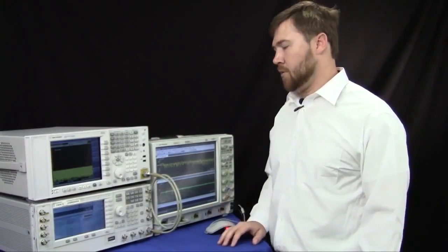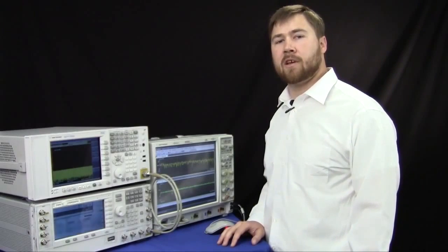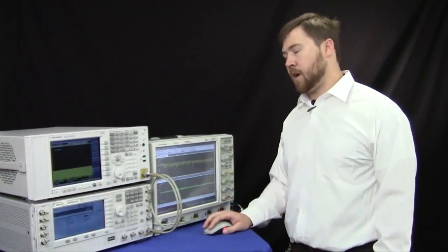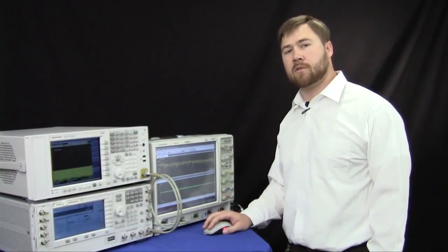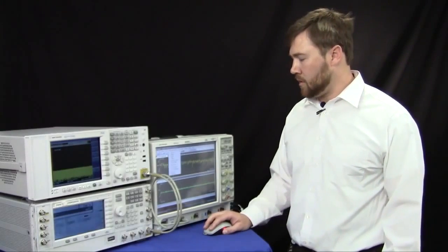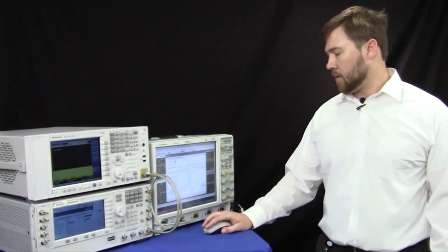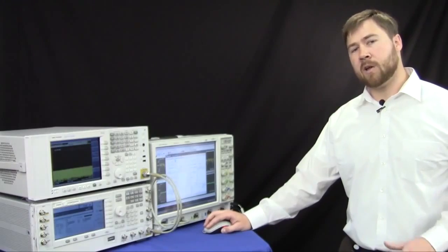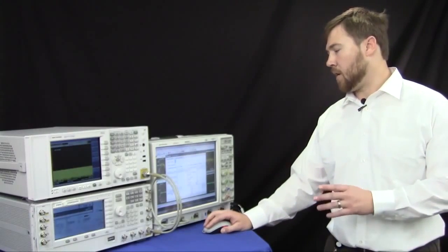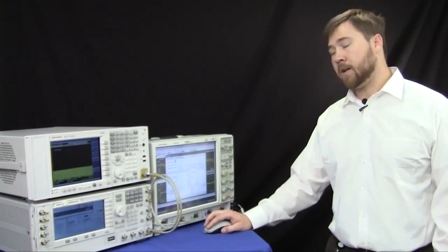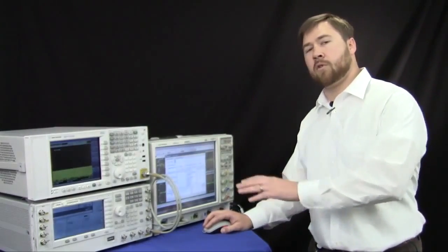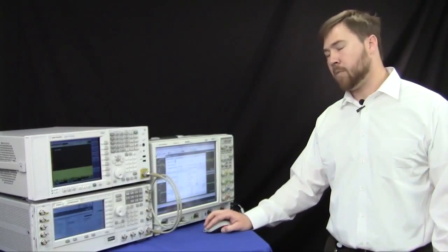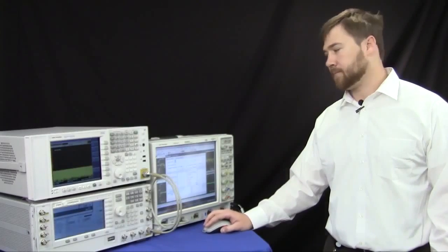I've programmed my source for a center frequency of 10 gigahertz, sweeping 900 megahertz wide at a constant amplitude. Then I'm going to come over here and set up my vector signal analysis software for use with a down converter. So I'm going to go Input, User Correction. Then I'm going to check this frequency converter box right here. And then I'm going to enter in all the same parameters that I put in the PXA. So I have an RF center frequency of 10 gigahertz, an IF center frequency of 700 megahertz, just like I programmed over on the PXA, and then 900 megahertz of IF bandwidth. And I'm going to invert my spectrum since we're high side mixing on the PXA.